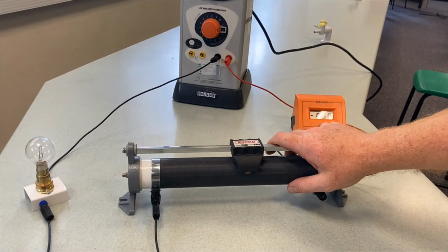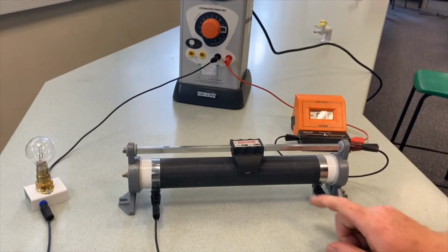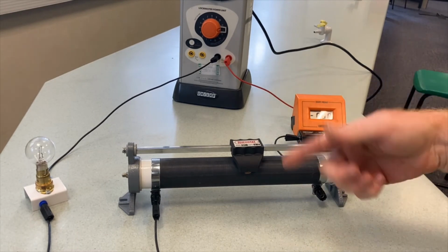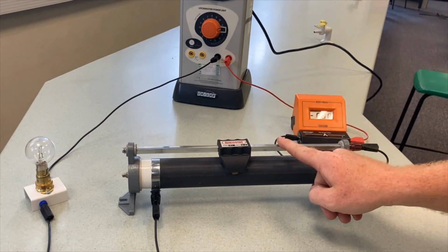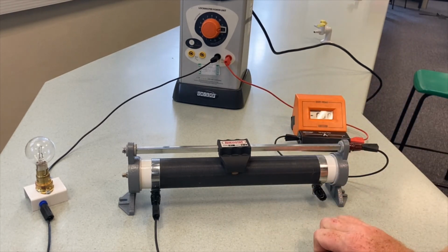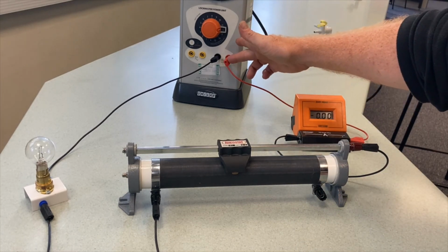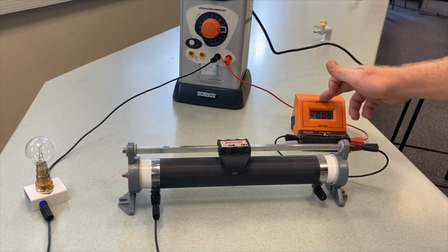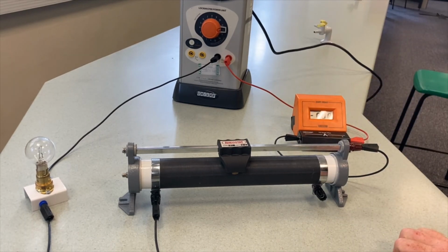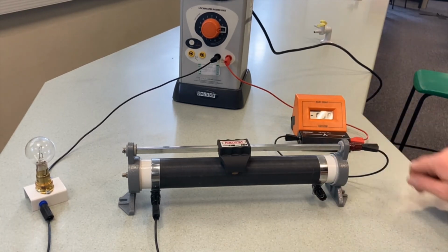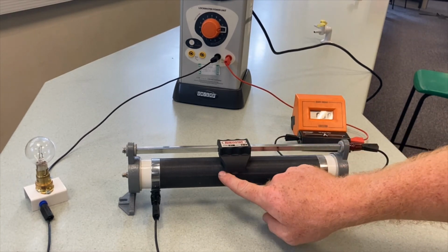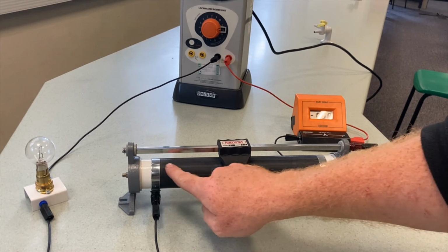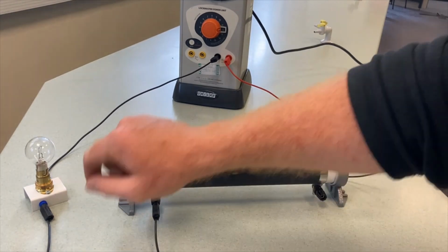So this here is a rheostat set up as a variable resistor. This black coil is wound round the drum, and this slider can be moved left or right to change where this bar is coming into contact with that coil. Current flows from positive to negative, so we're coming from the positive terminal of our power supply through our ammeter. That's just there so we can see what effect moving this slider is going to have on our current. We're then going to run along this bar to the slider, down into the coil, and then we're only going to pass through this section of the coil before coming out through our lamp and back up to our power supply.